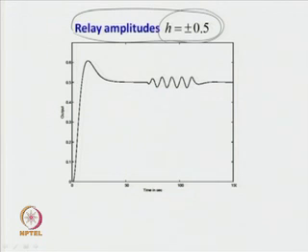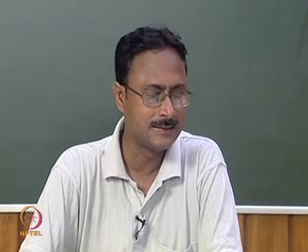So, what do we observe from here? We get symmetrical limit cycle output signal. So, if I draw correctly, then I will definitely get the symmetrical limit cycle output signal, and there is the beauty of this scheme, that in spite of the presence of the reference input, the limit cycle output is symmetrical.